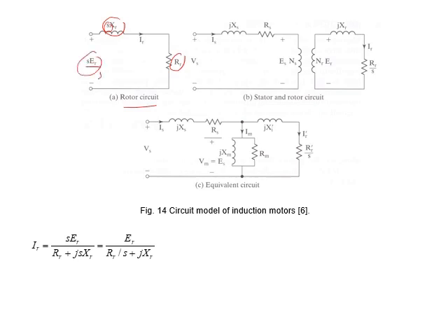So if I divide everything here over s, then we have here X, as you can see here. So if we put them together, stator and rotor, we have here the X and R for the stator and X and R for the rotor. These are the voltages and the turn ratio. And if we put them in an equivalent circuit, we just need to add in between stator and rotor the core elements, which are X and R in parallel.